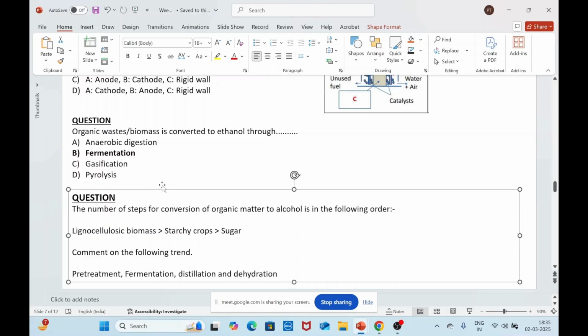True. So it is the cellulose that is the only thing which is actually going to contribute towards the energy production. The lignin is something more inert, which will not be suitable for the energy production, or will not basically contribute towards it. And the reason why lignin removal causes a larger number of steps is basically because the hydrolysis of lignin, if you see, is very slow. So that is one of the main reasons why the number of steps is more.